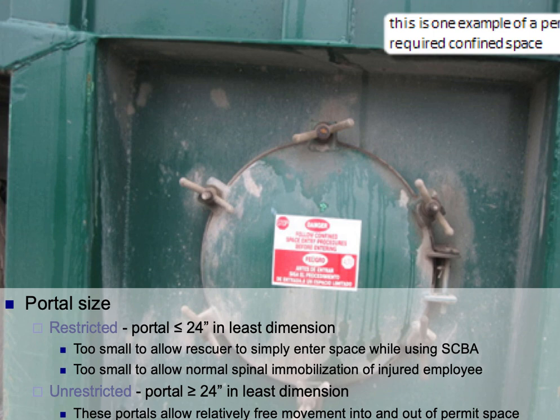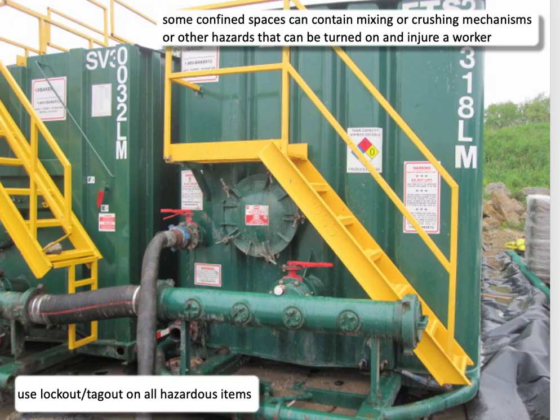And so unrestricted, it's greater than 24 inches and allows free movement into and out of the space. This would not be permit required. Permit required, it's less than 24 inches and/or is difficult to come into and out of.